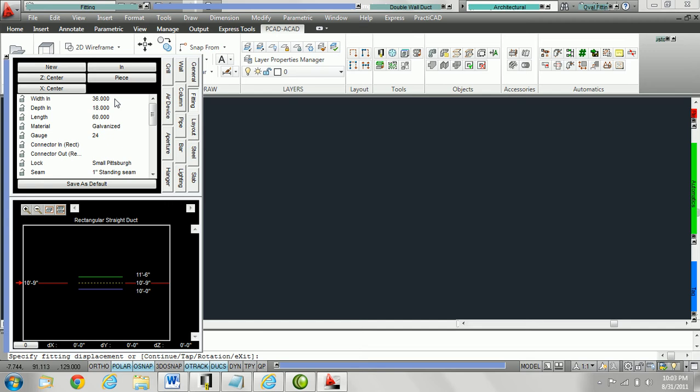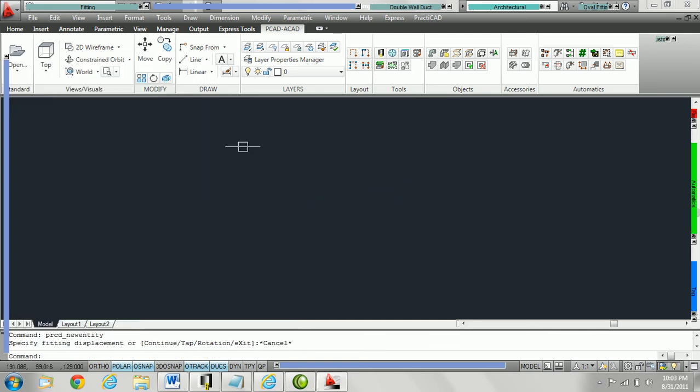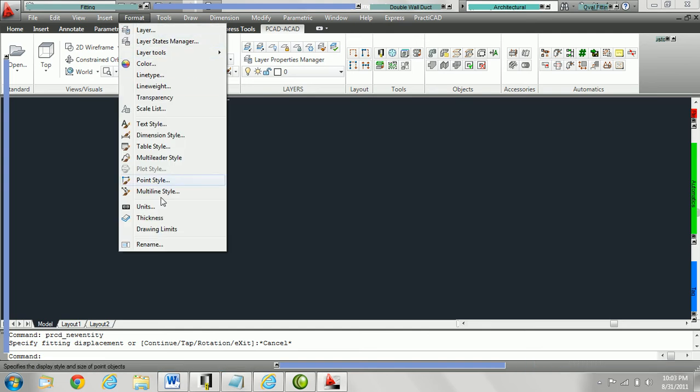36.000. The format is what AutoCAD calls decimal. The precision is 3 zero places. If we would like to be able to input values by feet and inches, we can change the units and save it to our template. To do this, we would come up into the menu bar and click on Format, and then come down to where it says Units. Now this choice might be different dependent upon the year and version of AutoCAD you have, but generally it's under Format, Units.